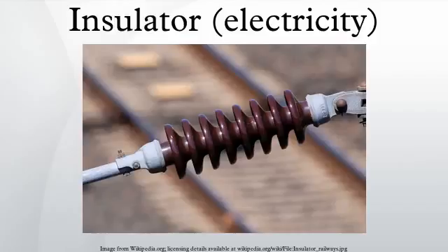The air in a region around a high-voltage conductor can break down and ionize without a catastrophic increase in current. This is called corona discharge. However, if the region of air breakdown extends to another conductor at a different voltage, it creates a conductive path between them, and a large current flows through the air, creating an electric arc.